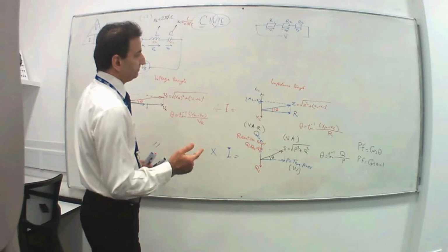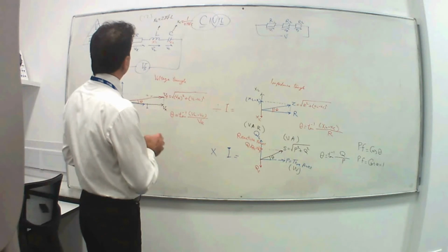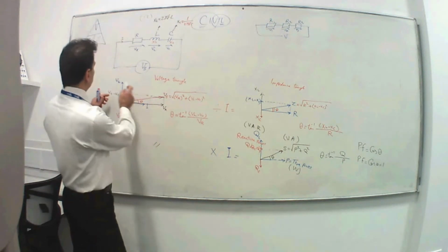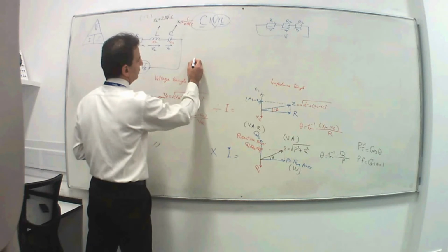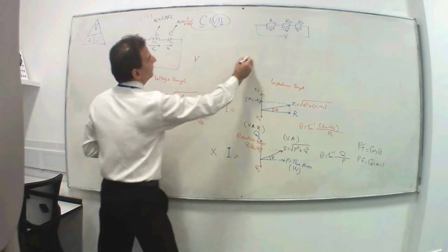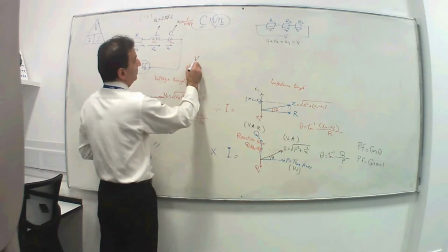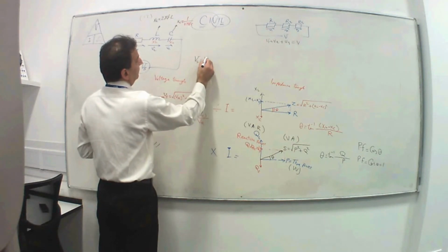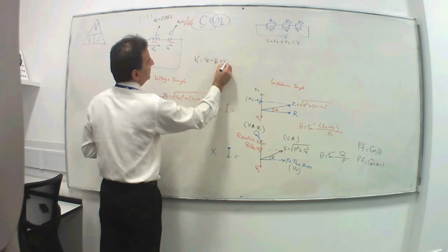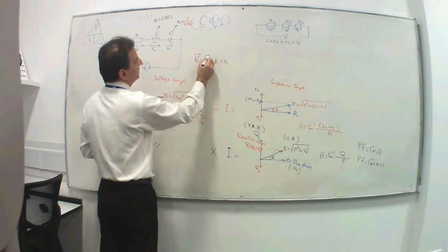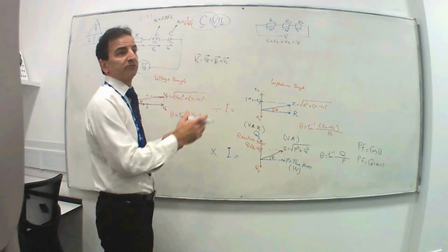Anything else missing here? Yeah, if you wanted to write this in Kirchhoff's equation, you say V1 plus V2 plus V3 is V. You could say VS here is VR plus VL plus VC, but you have to make sure you put vector signs on top of them, so that whoever reads this knows this is not just an algebraic sum.